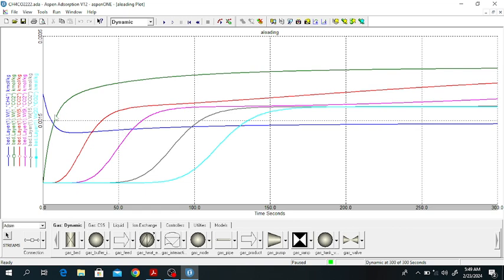At the first node methane is decreasing, but the carbon dioxide is increasing. The carbon dioxide is loading. The carbon dioxide is adsorbing, but methane is desorbing at node number 1. At the beginning of the adsorption column, methane is decreasing and carbon dioxide is adsorbing. The carbon dioxide is attaching to the adsorbent particle inside the adsorption column.